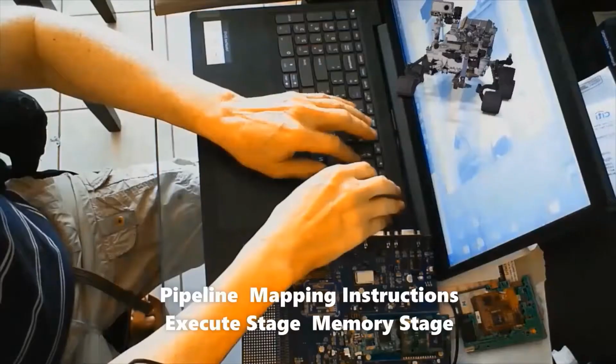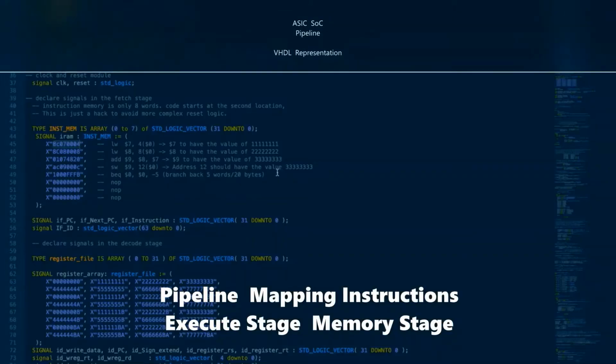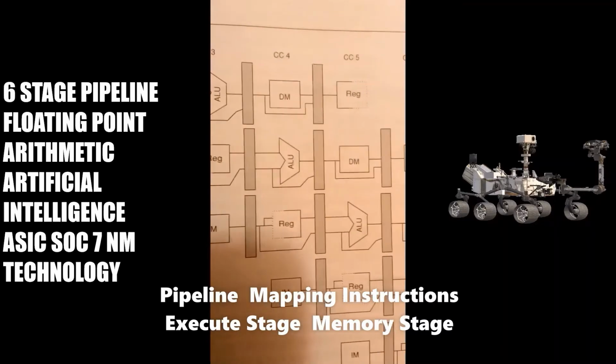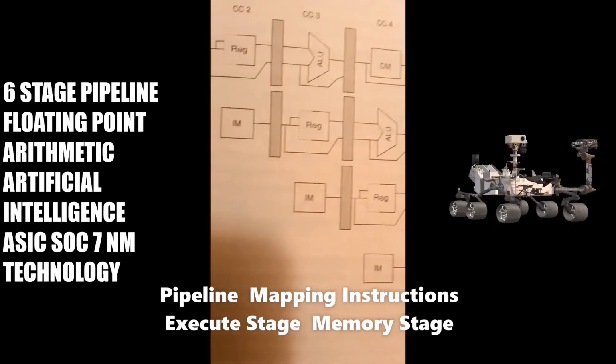The write-back stage writes the calculated value back to the proper register. It has input control lines that tell it whether this instruction writes back or not, and whether it writes back the arithmetic logic unit output or the data memory output.